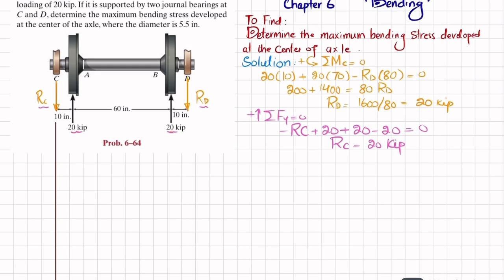First is this one, clear. From the end of this beam, there is a horizontal line which shows the length in x in inch. On the y-axis we have vertical shear force that will be in kips. Let each division be 10 kips, so 10, 20. Similarly, minus 10, minus 20, you can take as per your own scale.